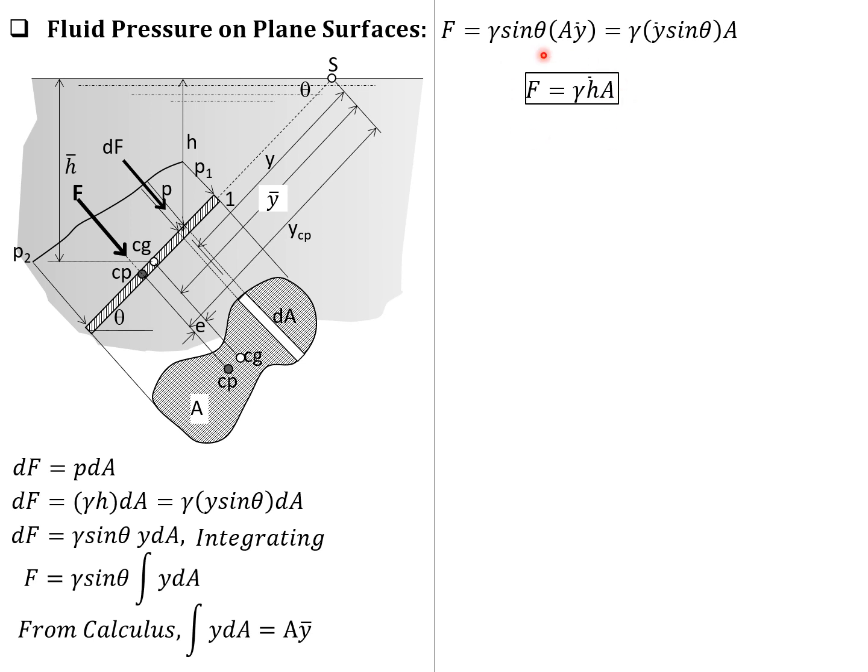So we use this formula whenever the surface area is in contact with one liquid and the liquid surface is exposed to the atmosphere, or the pressure is zero. But if you encounter a complicated situation, where we have a liquid here but there is pressure specified on top of the liquid surface, or this area is below layers of different liquids, that would be a complicated situation.